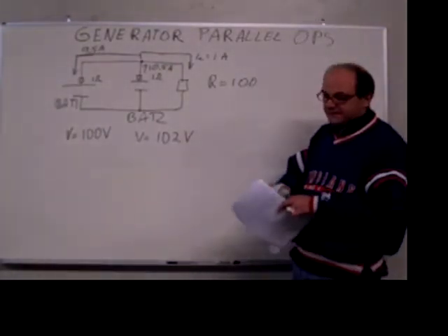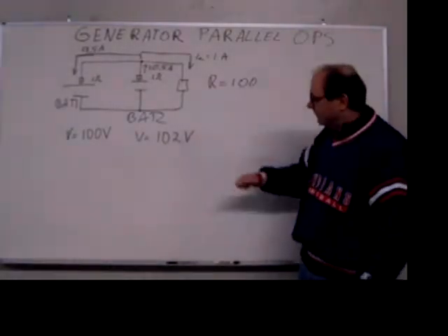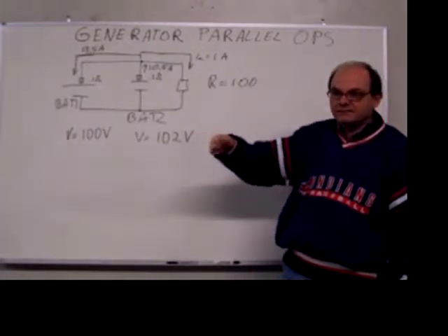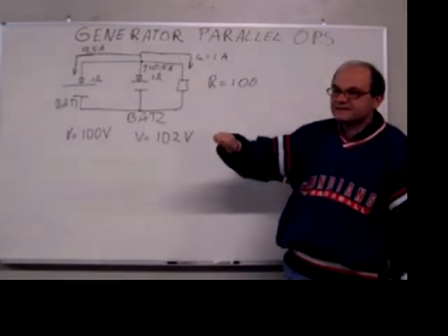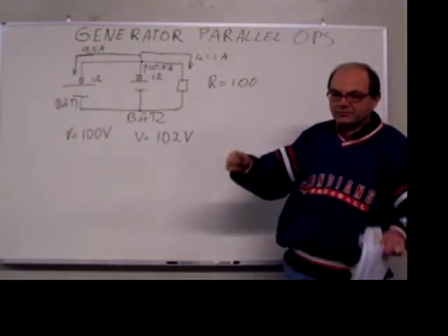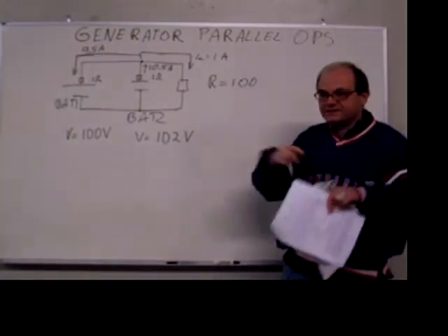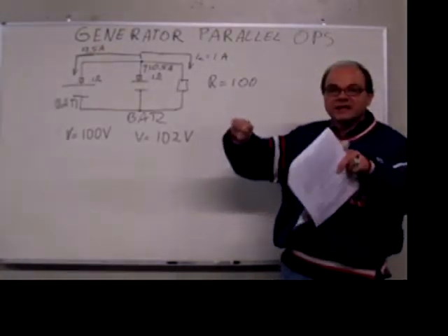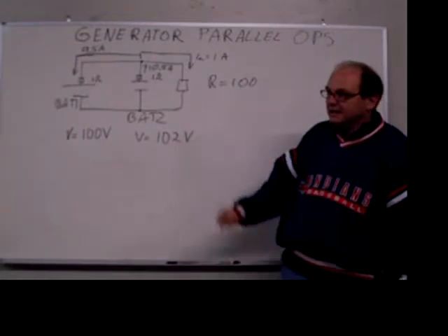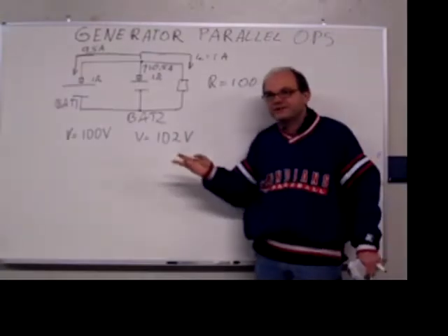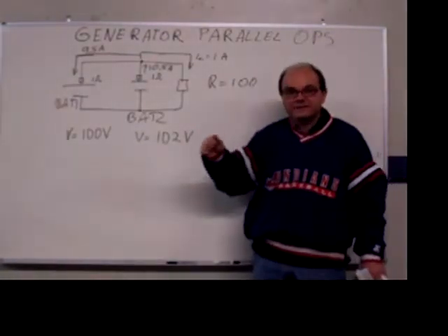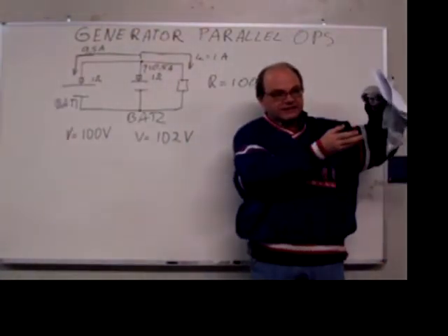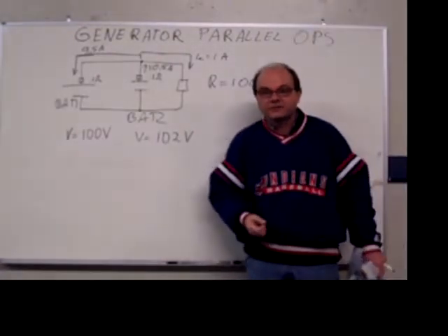Now, if, for instance, we had a circuit where both of the rheostats, which they call them, which are basically potentiometers, bigger size potentiometers, would be controlled, so each generator controls the other rheostat automatically according to the voltage, then you can actually level this out. The voltage on the O2 and O3 series are basically controlled by the rheostat, which feeds into the voltage circuit board, which is on the left-hand side inside the cubicle.